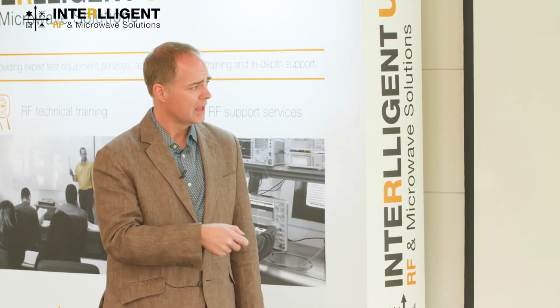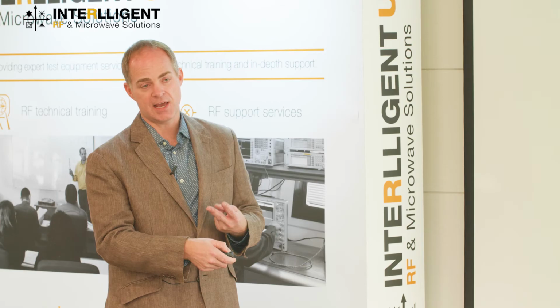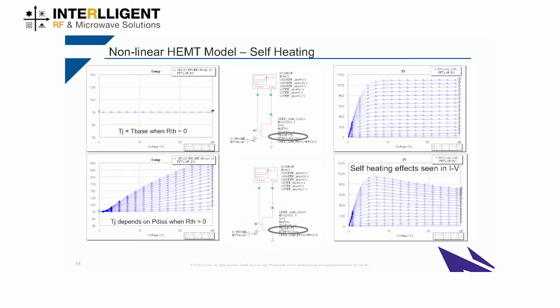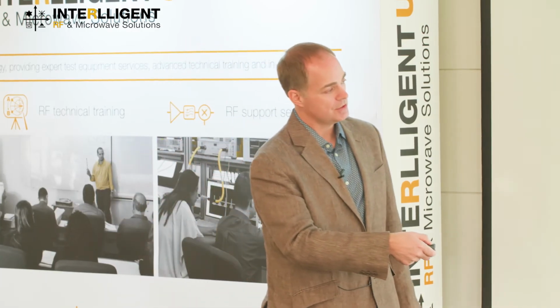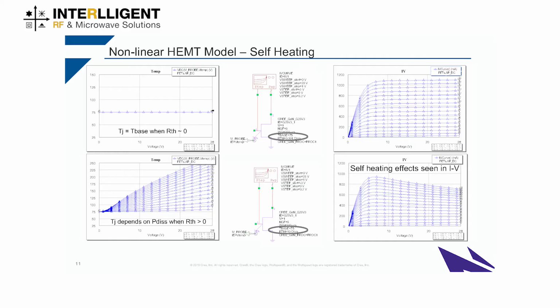However, if we add some thermal resistance, such as you would actually see when you mount this thing into an application, run it at CW, you're going to see as you dissipate more and more power, the junction temperature is going to increase. So out here where we have very high currents and very high voltages and we're dissipating a lot of power, we're starting to hit that 225 degrees C junction temperature limit. And this is useful for two reasons. A, so you can understand the impact of that on your actual performance. And B, you want to know what that junction temperature is in order to make sure that you're within the reliability limits of our device. And then also you can actually see in the IV plane that you do start to see the droop effects of this as you increase the power.